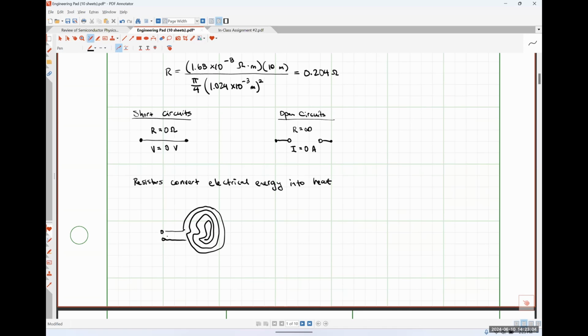So if we coil it up like that, we get a very, very long length for our resistor, while the cross-sectional area is effectively constant, and the footprint on the stove stays effectively fixed. So some are smaller, some are larger because they're meant to handle different sizes of pots, but they all operate the exact same way. Okay, so they're coiled like that just to make them really long.